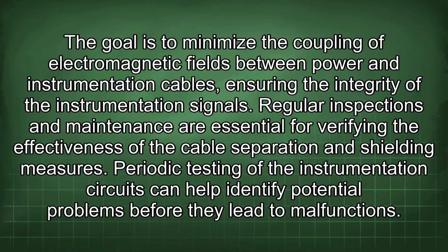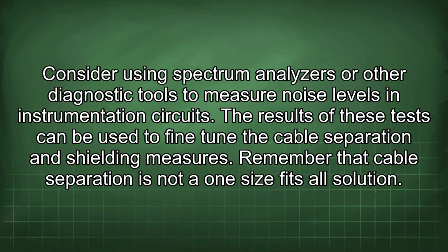Periodic testing of the instrumentation circuits can help identify potential problems before they lead to malfunctions. Consider using spectrum analyzers or other diagnostic tools to measure noise levels in instrumentation circuits. The results of these tests can be used to fine-tune the cable separation and shielding measures.